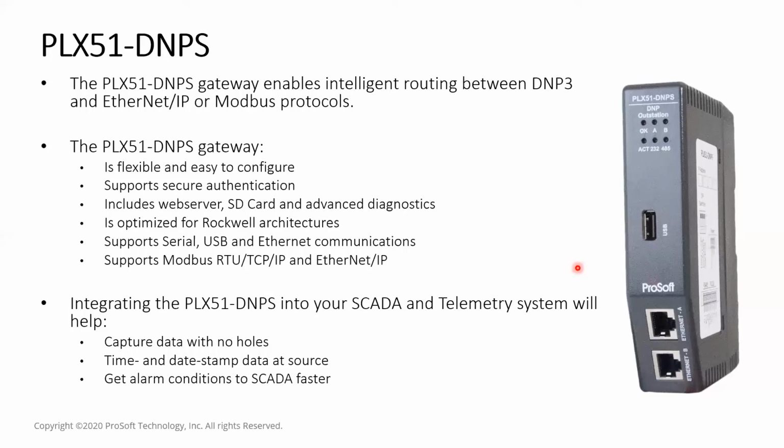So again, a big advantage where you've got a communications failure, and then this would ensure that because data is getting logged, you can get that data back all the way to the top end. The ability to time and date stamp at the source. One of the key advantages of the protocol is that it does support time stamping natively.